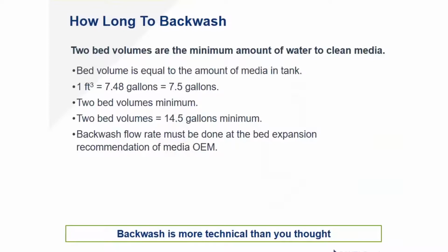So how long do we need to backwash? Well, 2 bed volumes are the minimum amount of water to get a clean media out of the tank. Bed volume is equal to the amount of media in the tank, and we're discounting the space that the media takes up. We understand that.